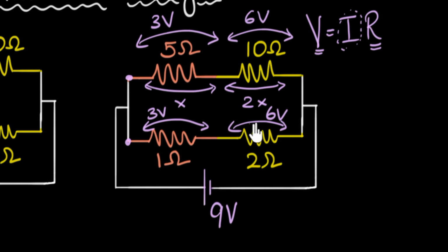So what? What does that do? Well, now let's look at the voltages at these 2 points. To do that, remember, whatever is the voltage here, same is the voltage here. So the voltage here and here is exactly the same, isn't it? If you want to call that 9 and you want to call this 0, then this would be 9 and this would be 9 as well.